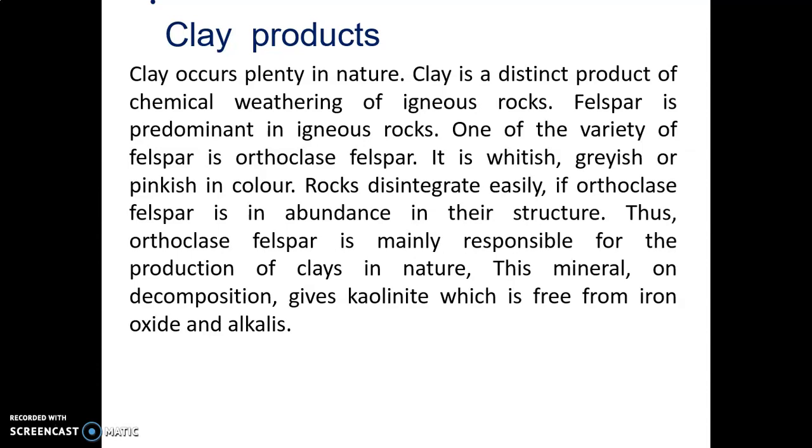Clay products. Clay occurs plenty in nature. Clay is a distinct product of chemical weathering of igneous rocks. Feldspar is predominant in igneous rocks. One of the varieties of feldspar is orthoclase feldspar. It is white, grey or pinkish in color. Rock disintegrates easily if orthoclase feldspar is in abundance. Thus, orthoclase feldspar is mainly responsible for the production of clays in nature.